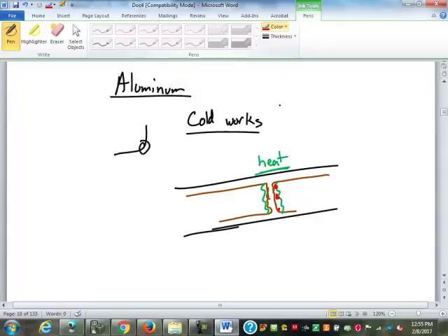It seems like less work to just rewire the whole place. Well, by the time you try to stretch wires through the walls, you're either going to have a really good fish tape, hopefully tie the wires together and pull them through, which usually doesn't work, or you're going to be punching holes in your walls. I've seen it where you cut holes like every foot, between every stud so you can drill through.